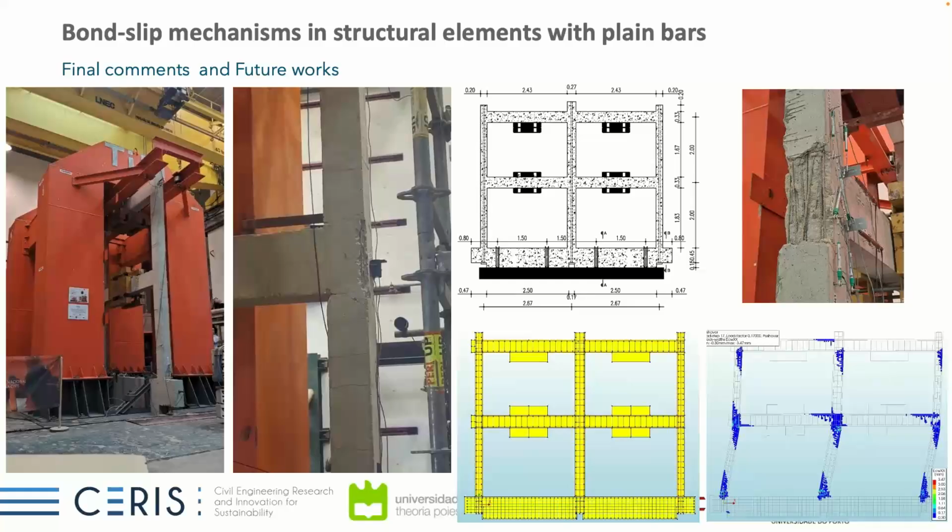And it's quite a nice thing, because now for nonlinear dynamic analysis, we have quite similar problems. As you can see here, the behavior is again controlled in the beam column joints, and we want to perform first pushover analysis, but later on nonlinear dynamic analysis in DIANA, to see if we can get also these results. This frame has exactly the same details as our beam column joints, just scaled to be able to be tested in this shake table test.